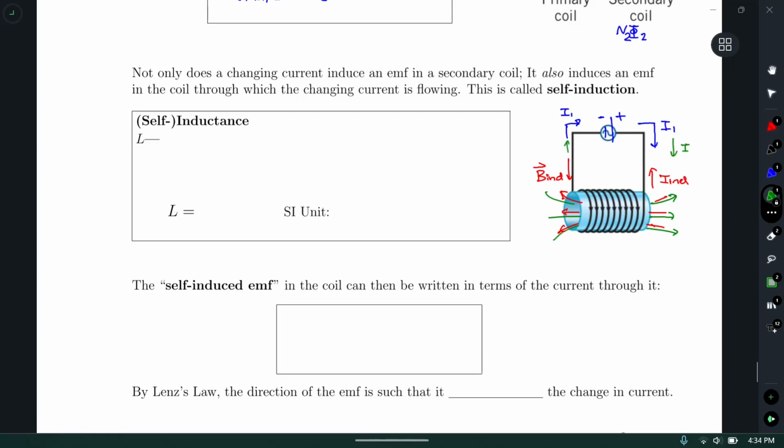And generally, the battery or generator is going to be stronger than, in this case, the induced EMF that is acting like a battery coming from this coil. Its polarity, by the way, would be this right here, the induced one. But you can see the situation. It looks like two batteries opposing each other, sort of fighting each other, and that's like replacing them with one effective battery that's a little bit smaller.